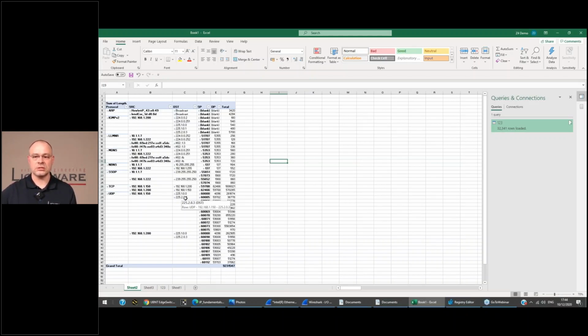Now, I did an actual test here, and I was able to put about 2.5% to 3% extra details on the network communication just by putting an extra pair of Wings on it. And I did not set up the IGMP parameters properly just to see how much data I'm putting on with my own products, with the Wings products. So in this case, 2.5% does matter if we have almost the 1 gigabit Ethernet limitation. When we're close to it, then we need to find out what is unnecessary in our network.